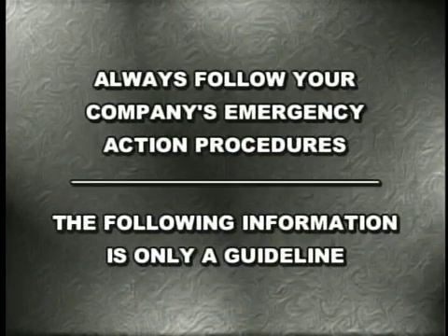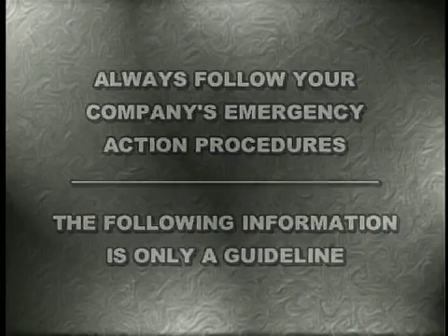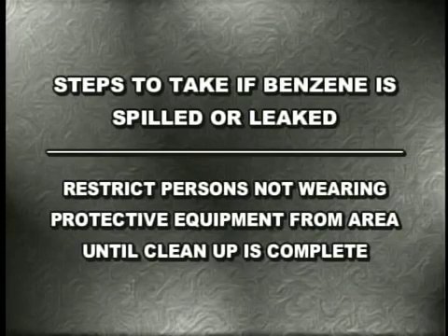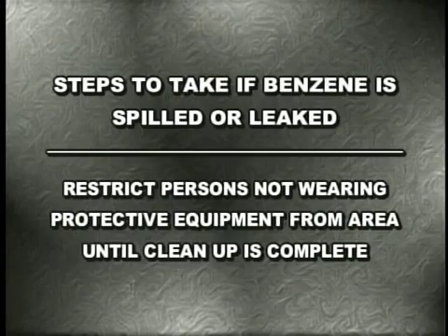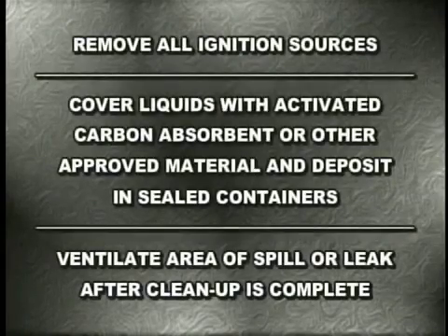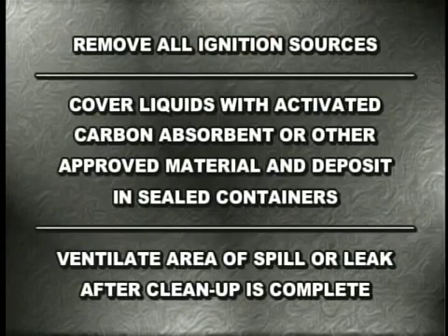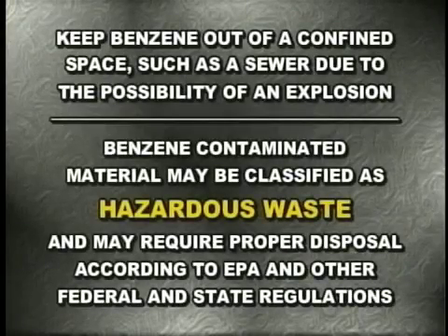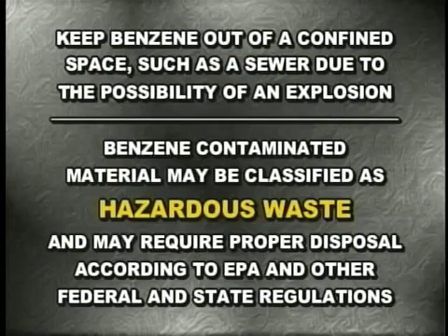Always follow your company's emergency action procedures. The following information is only a guideline. If benzene is spilled or leaked, take the following steps. Restrict persons not wearing protective equipment from the area of the spill or leak until cleanup is complete. Remove all ignition sources. Cover liquids with activated carbon absorbent or other approved material and deposit in sealed containers. Ventilate the area of the spill or leak after cleanup is complete. Keep benzene out of a confined space, such as a sewer, due to the possibility of an explosion.